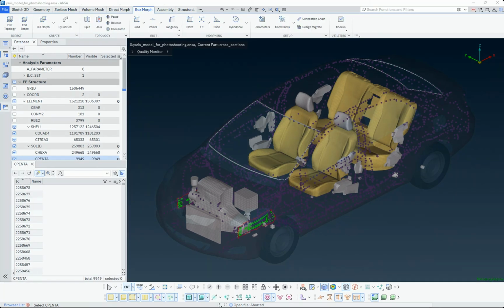To open the selection list for any of the items listed in the database browser, double-click on its entry, or select the Open option in the context menu. The Selection List window opens and, by default, is docked at the bottom left corner. The selection of listed items is made using the left mouse button. Selected items are marked. While in selection mode, selecting from the screen results in the automatic marking of the corresponding entry in the list. By default, the lists are sorted by ID in ascending order. Clicking on the ID column header switches the sorting order from ascending to descending and vice versa.